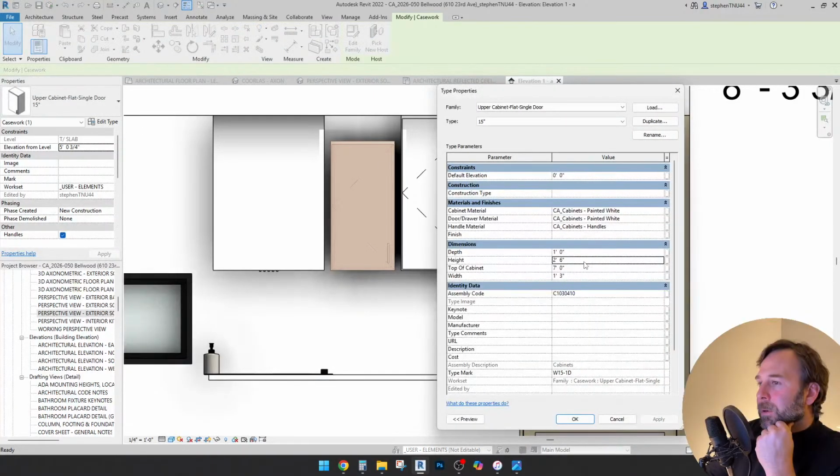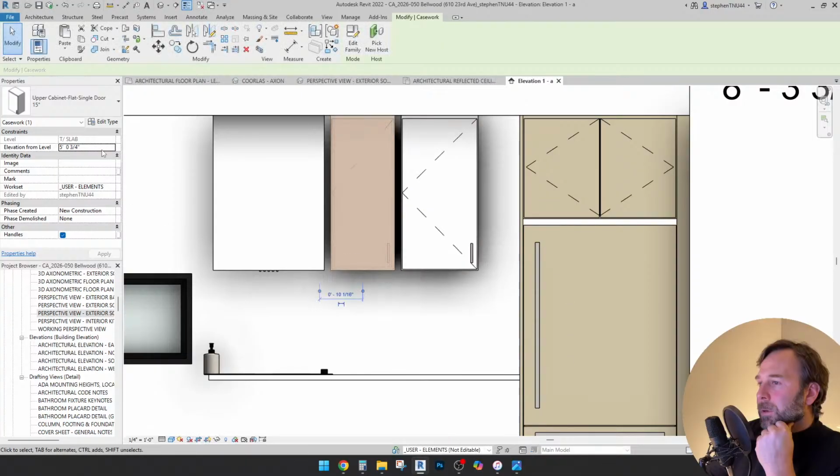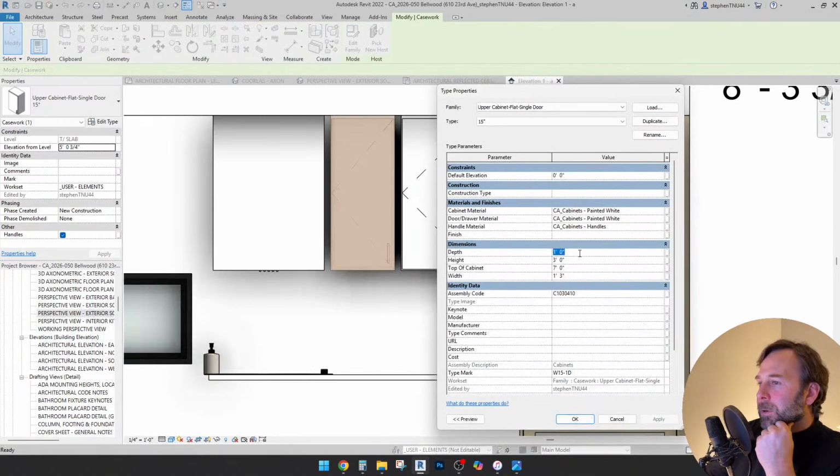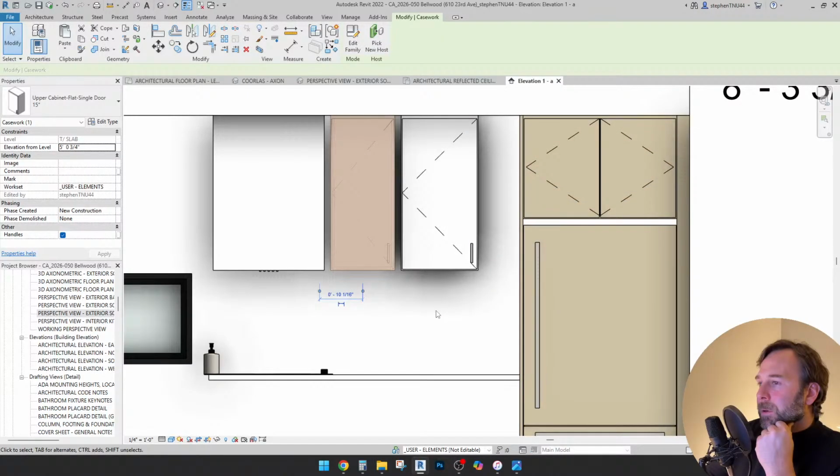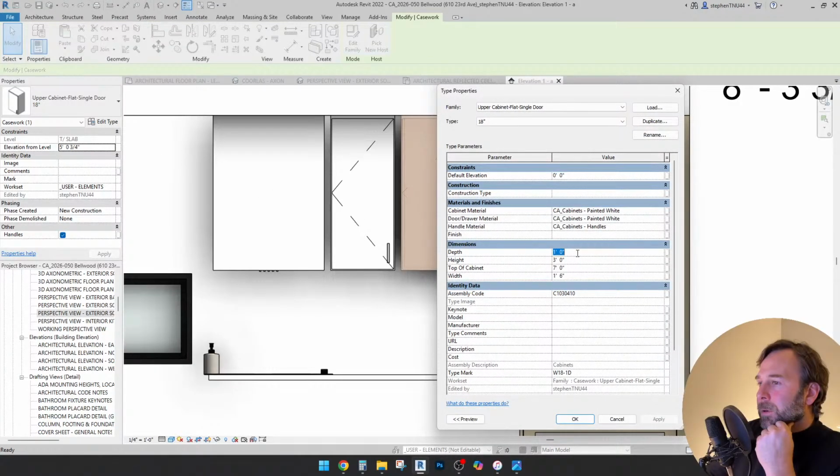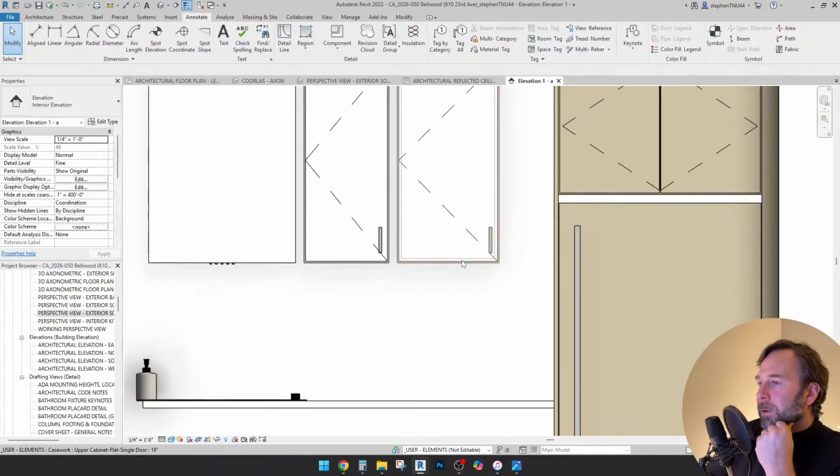Edit 3 feet height. The depth, I'll make them deeper, because we have the deeper countertop depths. Something to remember is if you have 30-inch countertop depths, you are going to want to opt for the deeper uppers. Sometimes they come in 12 inches, sometimes they come in 15. People don't like the 15 on the 12-inch countertop depths because they kind of protrude a little bit. Could be kind of head knockers. But for this application, it certainly works.